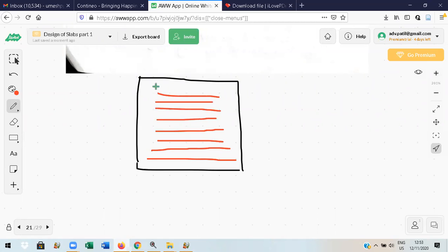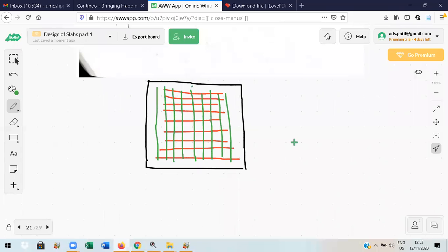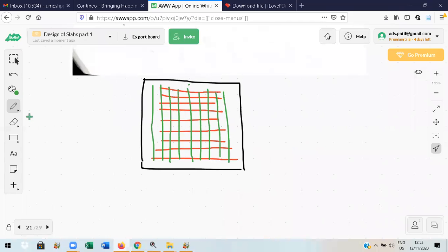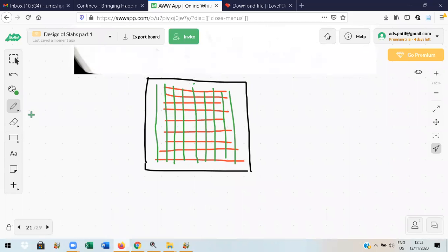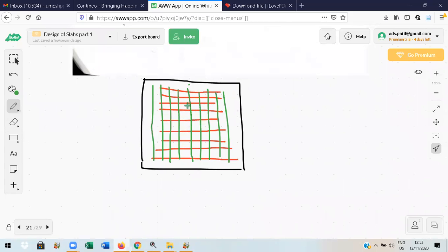Like this, you have to provide the reinforcement; how to provide it is a separate talk only. It cannot be covered in this. Then reinforcement along the longer span, Ly. Diameter and spacing we have to calculate, finding the bending moment using table 26. Reinforcement in the edge strip. So what exactly does it mean? Whatever I am showing here right now,